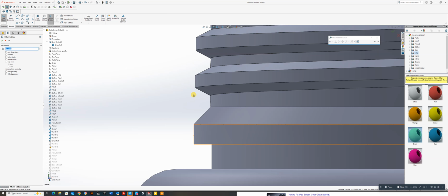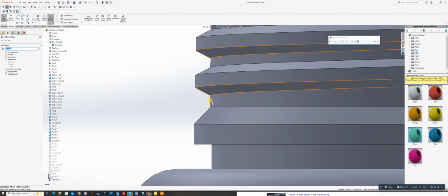See, I could do that one there. What you find is the thicken command, when you use it, it can actually distort things. For modelling purposes, not an issue, but if you're actually going to be doing stuff for tool making or something that involves 3D printing for accuracy, it can be.